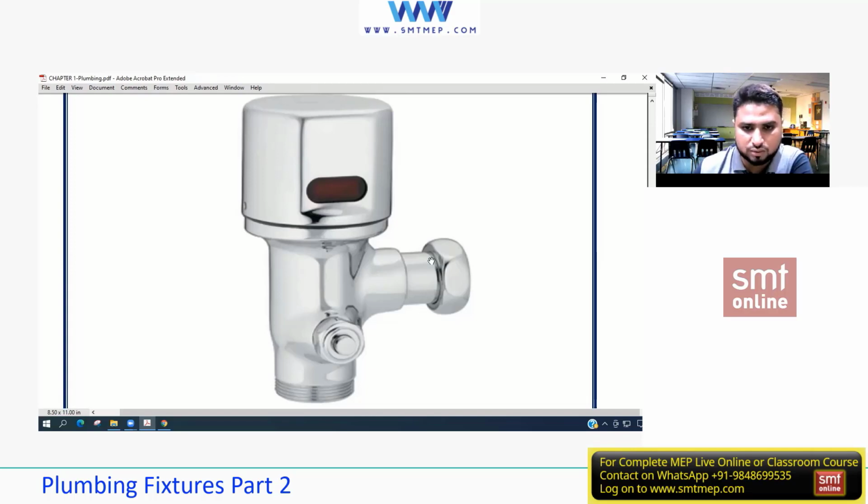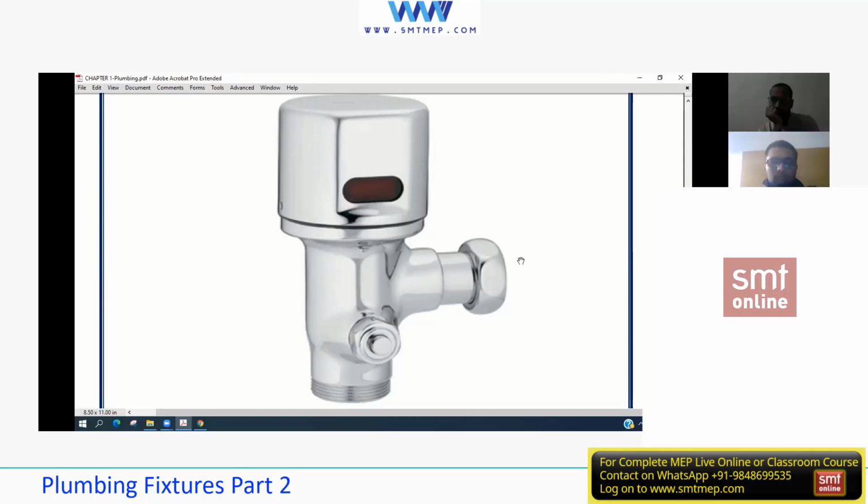Actually, I have recently installed these electronic flush tanks in one of our projects in Riyadh. This is a 4-star hotel. It was the demand of the Ministry of Tourism that the common toilets need electronic flush tanks. So I installed them myself. We provided permanent electrical connections, and the flush tanks we installed can be used manually or with an IR sensor.